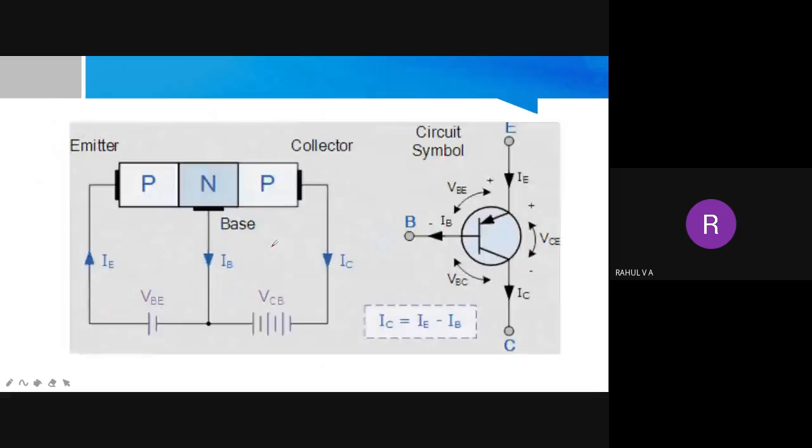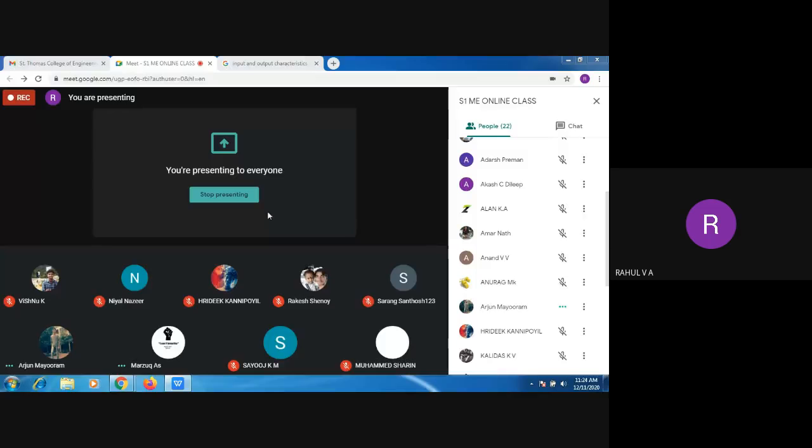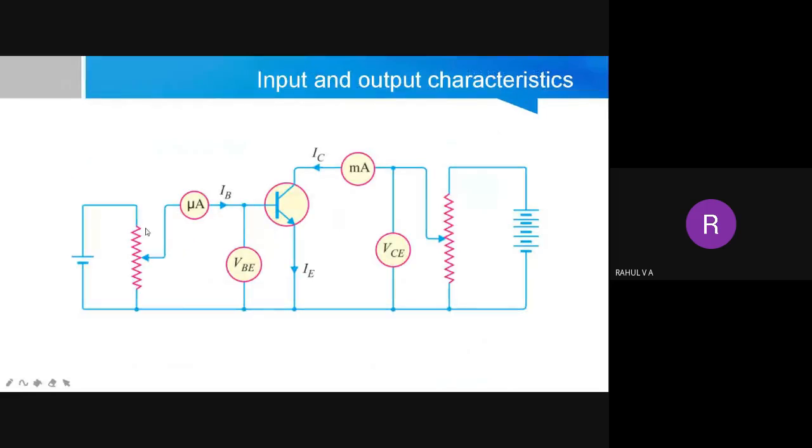If you rotate that knob, this voltage will vary. Which voltage? The voltage across this one. This is actually your first terminal, this is your third terminal, this is your second terminal of the potentiometer. So if you rotate this one, the resistance across the 1 and 2 terminals will vary, and the voltage at this point also will vary.